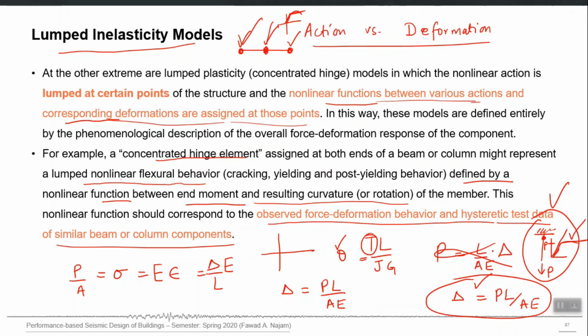So for any, let's say, beam or axial load, whatever is the action, like moment and rotation, like stress and strain, like axial load, axial shortening or elongation, torque, twist, shear force, shear deformation, it is applied in a cyclic manner, and at the end of that test we get the cyclic behavior, and that behavior guides us about what input we should use in the numerical model of those similar components, right?